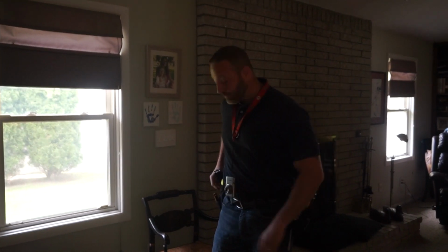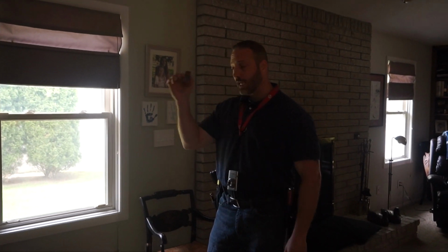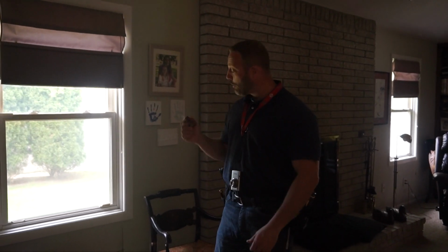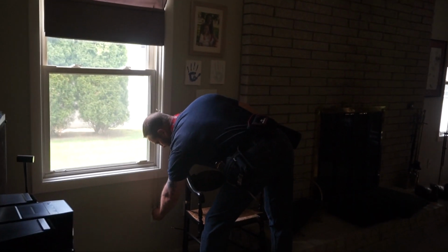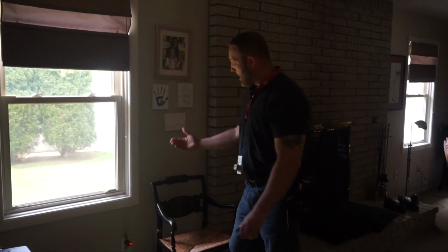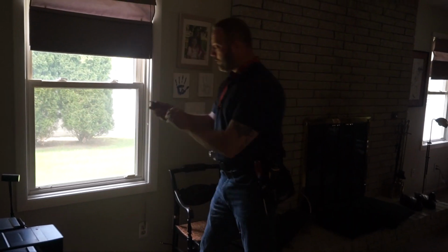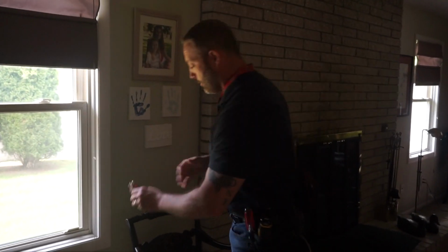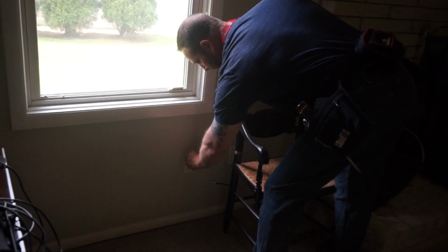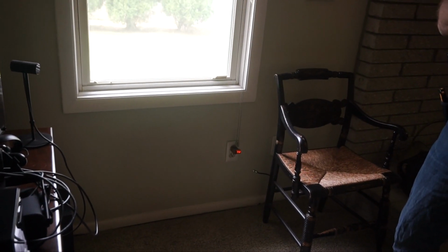So once we've tested a representative amount of windows in the general interior, you're going to take out your ground fault circuit interrupter, and we want to make sure that each of the outlets are grounded properly. This particular device shows with those two lights that it's correct wiring. So again, let's just place it in here. And that's showing that it's correctly wired and correctly grounded.